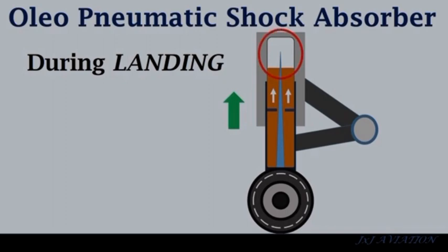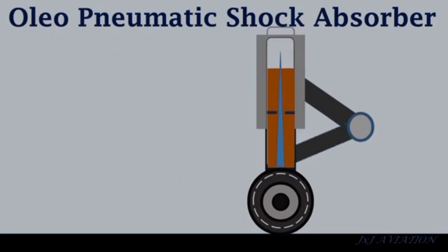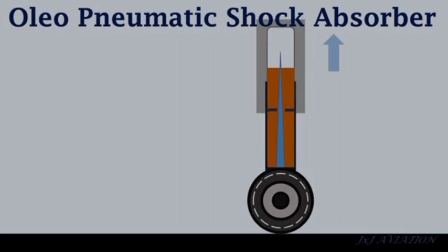But if the landing is so hard, for example with a very high impact, the shock absorbing characteristic of the landing gear will reach a limit, and then the linkages will be damaged. Mostly in some very hard landings, it has been seen that even the structure where the landing gear is attached got some problems, for example some deformation. This is a landing that should truly be inspected, and even sometimes the landing gear should be removed, sent back for the overhaul, and replaced with a new one.